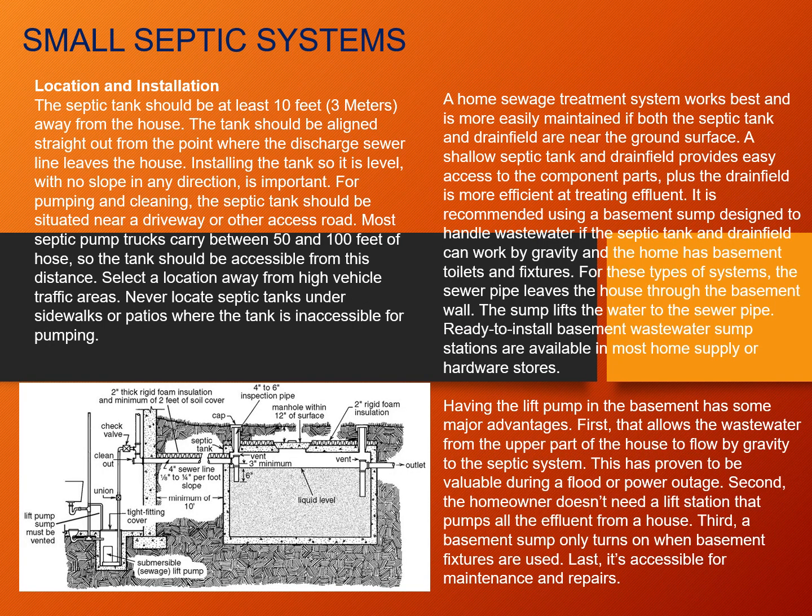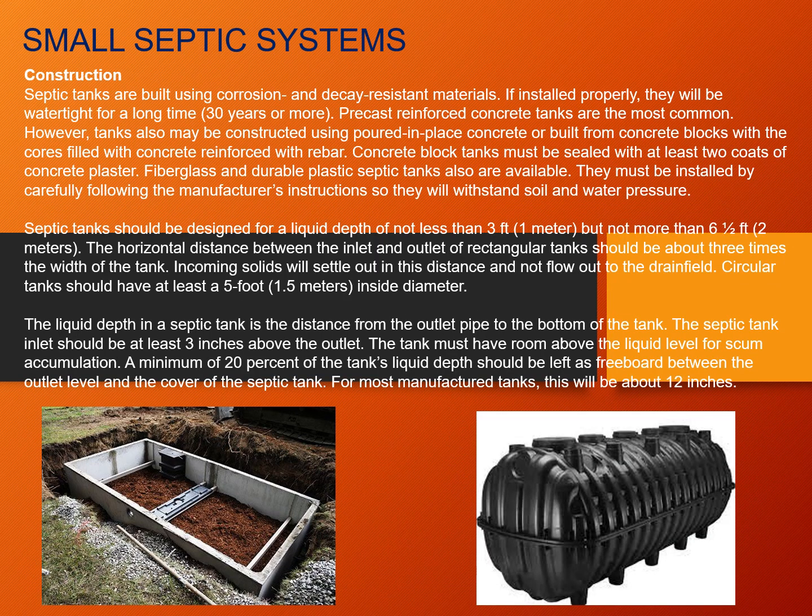Now, to locate your septic tank, it should be at least 10 feet or 3 meters away from the house. But if you have constricted spaces, then I would suggest referring to a sewage engineer or a plumbing engineer on how to install your septic tank. The 3 variations of constructing a septic tank are: one, poured in place concrete or concrete blocks; two, precast reinforced concrete tanks; and three, fiberglass or polyethylene plastic tanks.